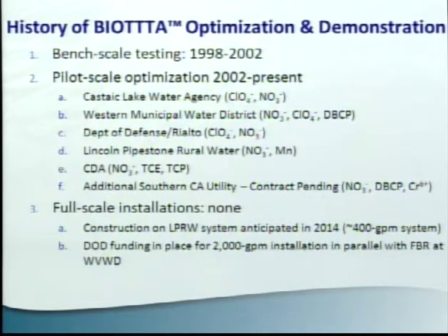We don't have full-scale installations at this time. We are under a conditional contract at Lincoln Pipestone in Minnesota, pending the results of the pilot study and approval by the Minnesota Department of Health for that system. That would be a 400 GPM system that we hope to have online by the end of 2014 or early 2015. At Todd's site, you mentioned there's that system down there at West Valley is a fluidized bed reactor system.